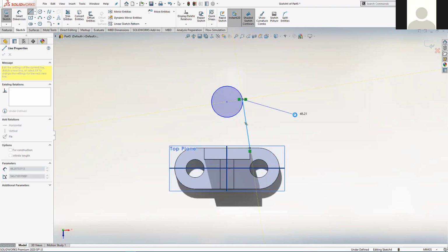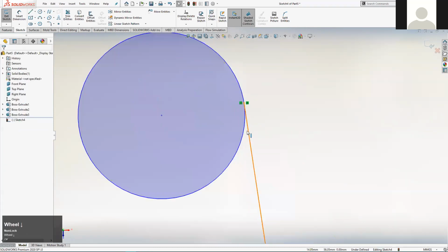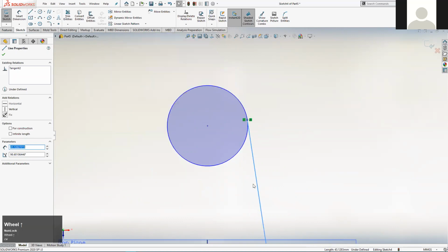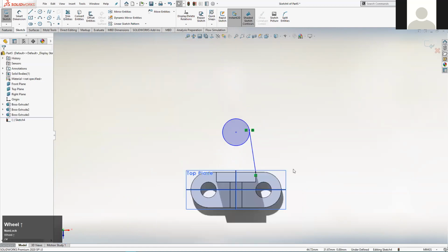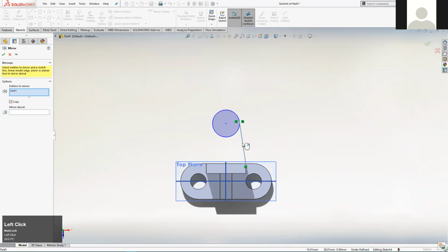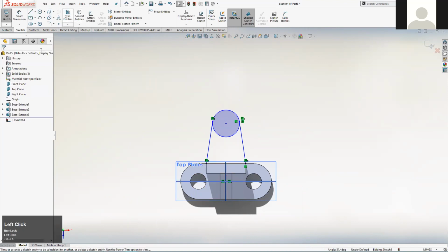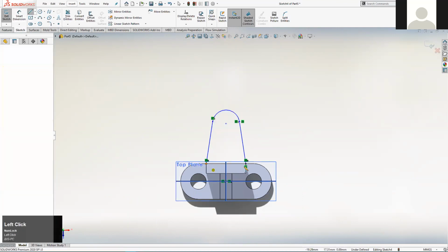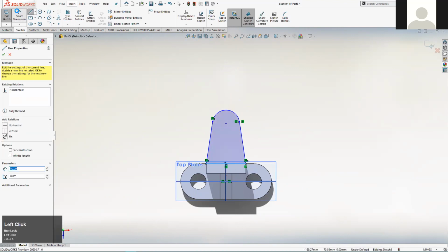That's what I want. So basically what that means is as the line comes towards the circle to meet it, there is zero angle between the two. So the line will run into the circle perfectly. There will be no harsh angle between the two of them. But we'll cover that when we do this a little bit slower. So back to what we were doing. Mirror that line using the mirror command. Trim some of the circumference, and then close our shape up again, like that.